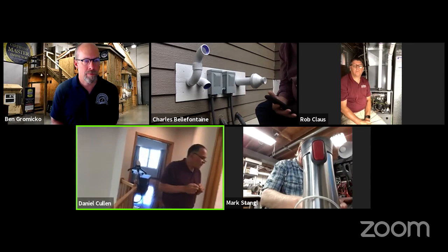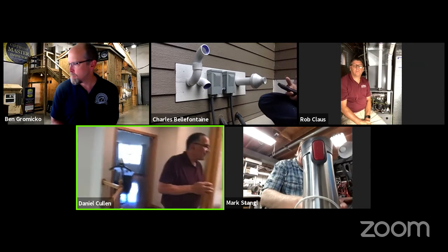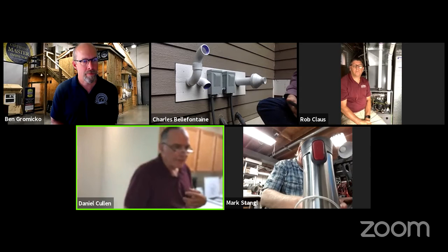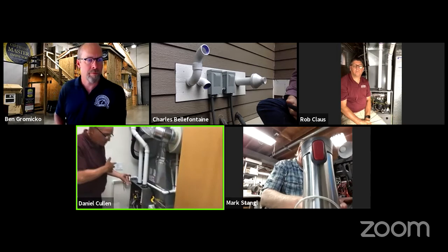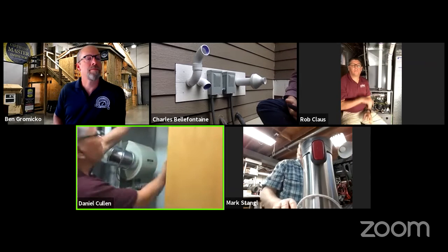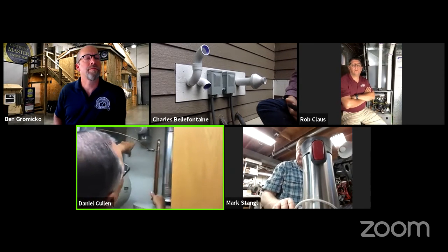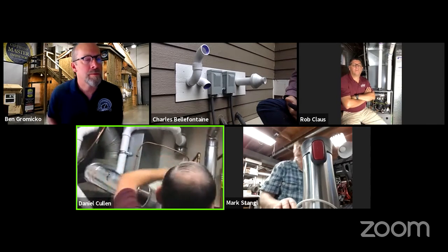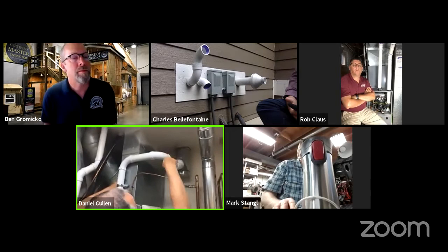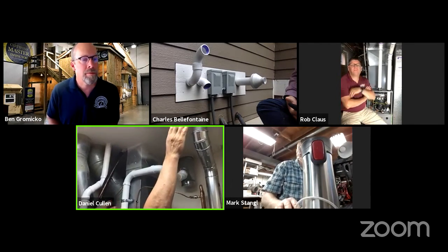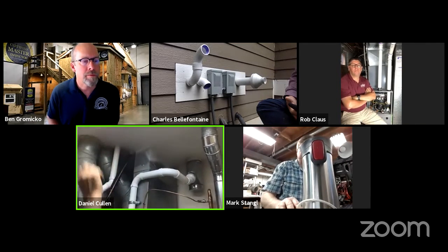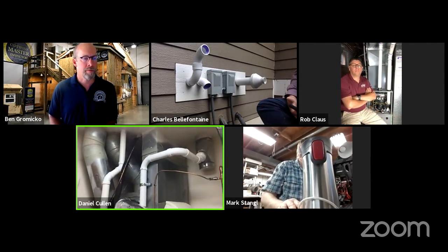So a couple months ago, I had a friend of mine, an HVAC contractor, come out. He took out the 20-year-old Carrier 80%er and put in a high efficiency sealed combustion furnace. This is 97% efficient, I believe. This was where the furnace, this is where combustion air came in for the combustion room. We closed that off. And this is where we took our exhaust out into the attic and up through a roof-mounted penetration. That's where our PVC pipe ends up.